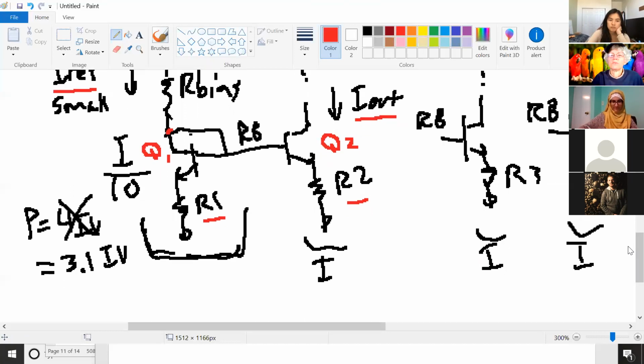Then we need to, in Circuits 1, when you did KVL and KCL, it's like, yeah, okay, that class is done, check. But KVL, KCL, that's what we're going to be doing the rest of the quarter. And so you need a loop that includes R1 and R2. And there's really only one. You want a single loop that includes R1 and R2. That's your KVL loop.